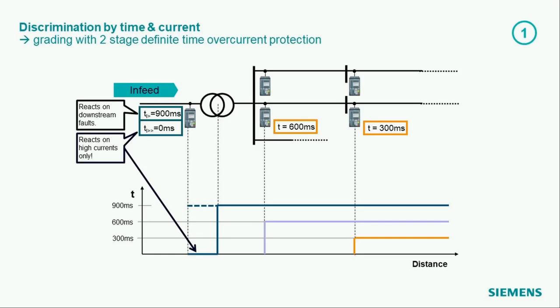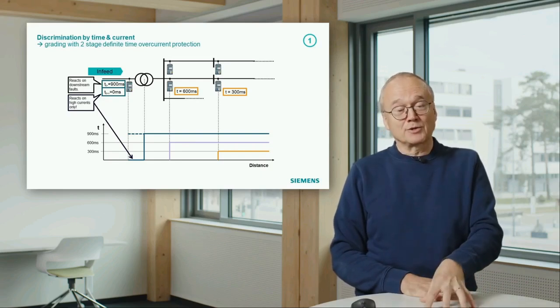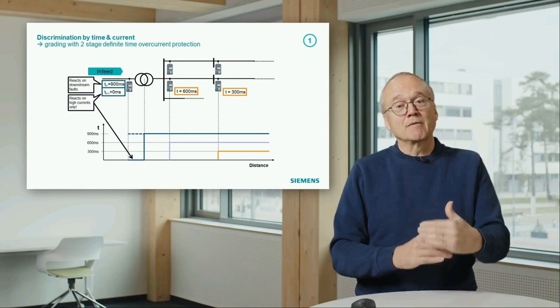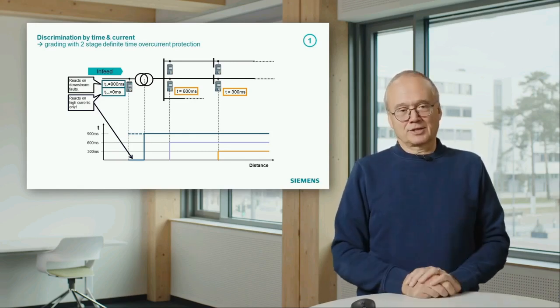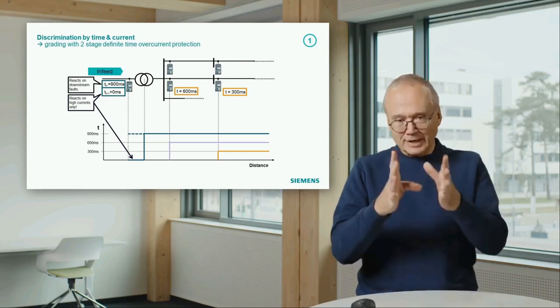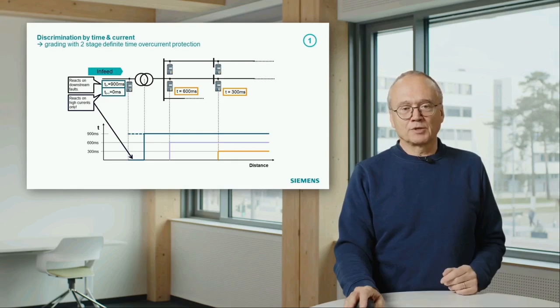And then it can trip faults on the high voltage side of a transformer without time delay. That means we must do short circuit calculations for the system and then make the timer setting in an adjusted way. That is a thing what you often find in connection with transformers.